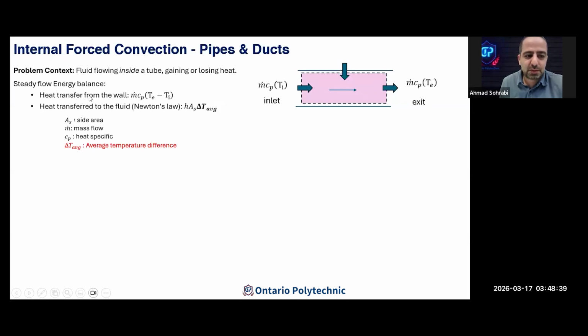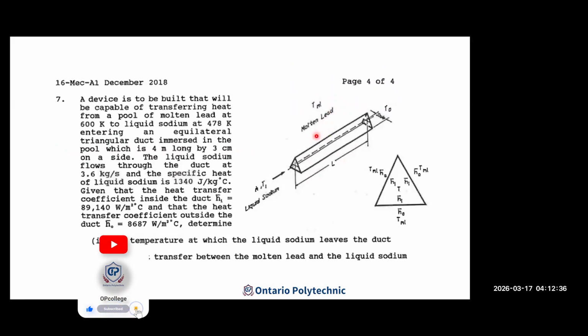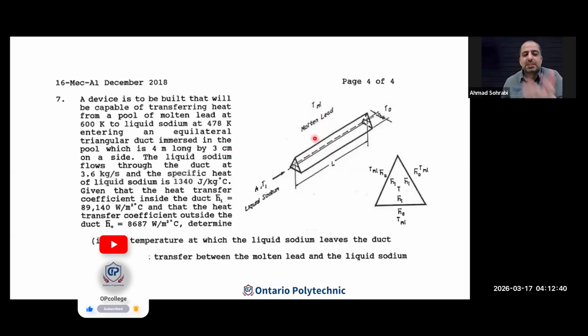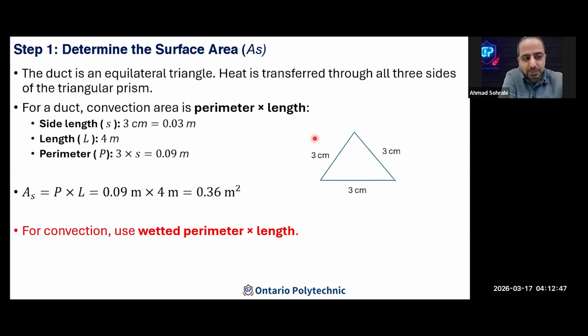So the heat transfer, because of the moving of this fluid, is m dot Cp times the temperature difference. M dot is the mass flow, Cp is the specific heat, and the temperature difference is between outlet and inlet. It's a constant temperature, yeah? Yes, it's a constant temperature. And the surface temperature, we can assume here, is 600 Kelvin.